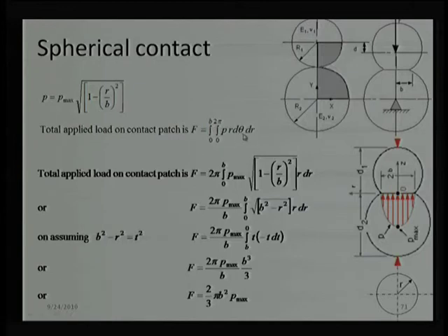It will be theta outside, and substituting the value of theta as 2 pi minus 0, it will be 2 pi. So, 2 pi is common, P max. This is in terms of R under the dr. So, we can take B as common again, and P max is common. The whole expression is square root of B square minus R square into R into dr.